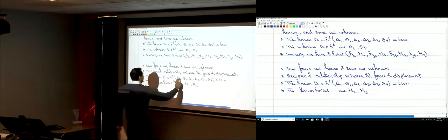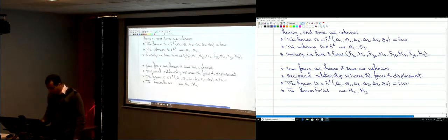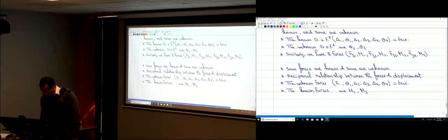Here you have the known degrees of freedom. That means that the equivalent forces are unknown. So I'm just going to remove this and put the unknown forces. Delta 1, so that's equivalent to Fy1. Theta 1, so that's M1. Delta 2, so Fy2. Delta 3, so Fy3. Delta 4, so this is Fy4. Theta 4, so that's M4. And those are unknowns.